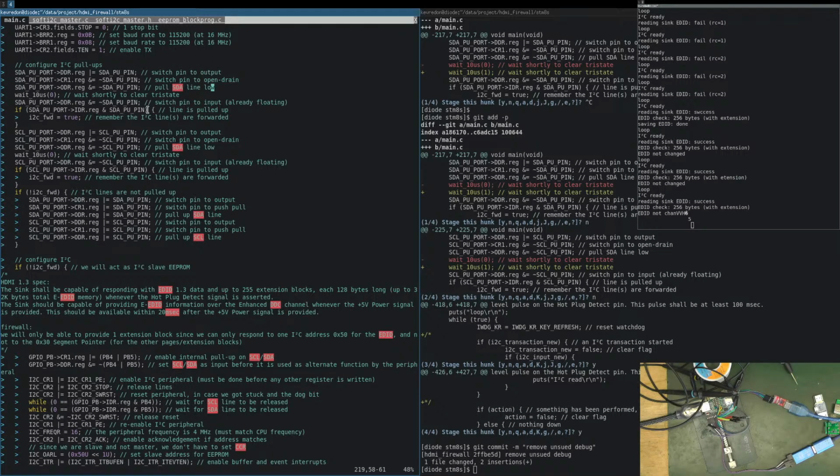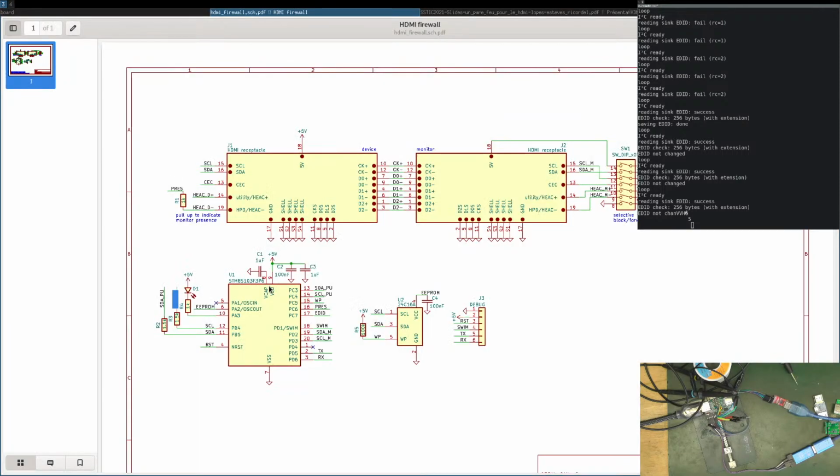How do I do it? I have to use the SDA lines myself and then pull high and low and test. Let me check. Here I have the SDA pull up and then I have SDA here. Okay, so I just need to pull up these two lines low and check if they're low here. I could also do it here, but the problem if I do it here, no, it's not really a problem though. No, I could also do it here. I just don't do it here. I have this already configured. So I will pull low and high here, and I will measure if it's low and high here.